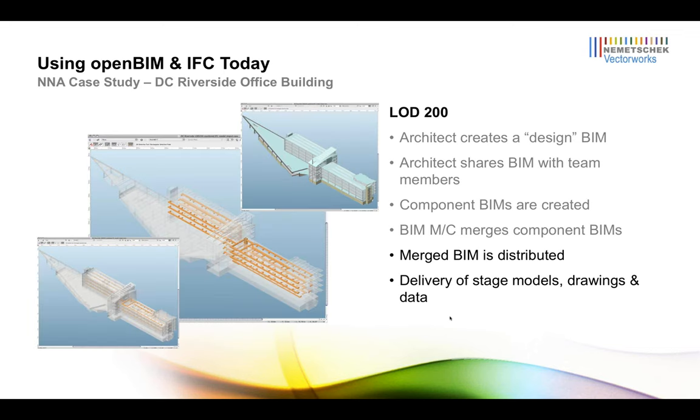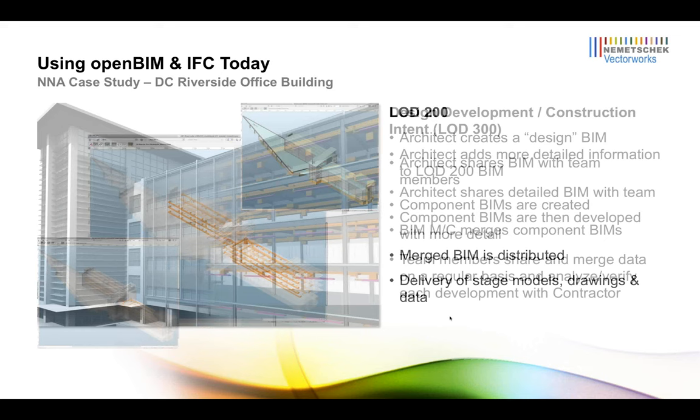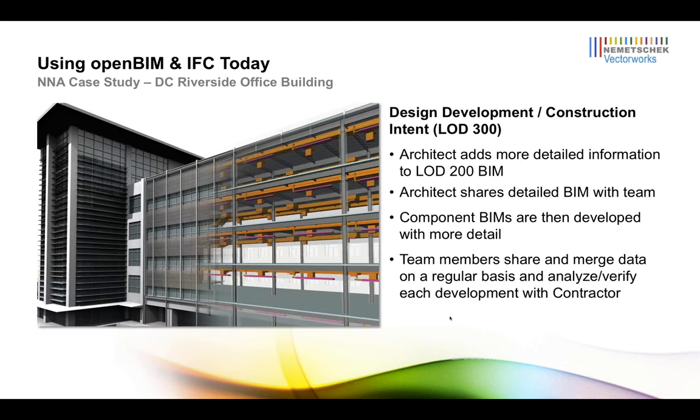They all have an agreement on how far they want to develop in terms of detail. Then that merged BIM is distributed and given to the contractor who can do a quantity and cost analysis. And the design teams can then take that as a reference and go back and begin to develop their design even further. And this continues on for the LOD 300 part of the process too. And as I said, all these models and the information about this project are available on our website, so people can look at this and see how this process works.